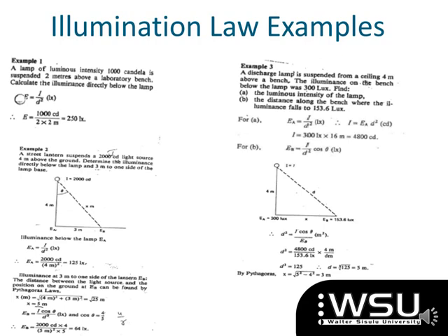Now I just want us to take a step back to see exactly what we did here. In the first example, we had the 48,000 candela, which means we worked out what I was. That I, your light intensity, doesn't change irrespective of the illuminance or where it is in reference to your source; your intensity of light is always going to be that same value.